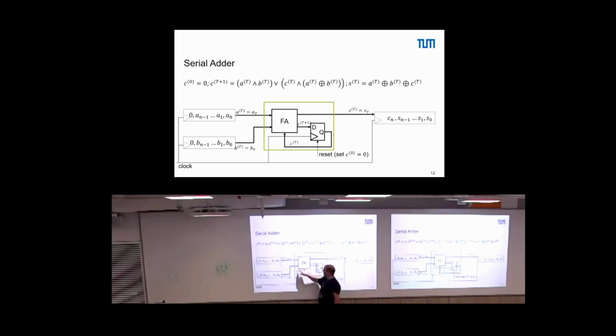In the next time step, we add A2, B2, and the carry, and so on, until we have reached A(N-1). Yes, it's just the same principle as we had for the subtraction. If you apply here 0 as a carry in,